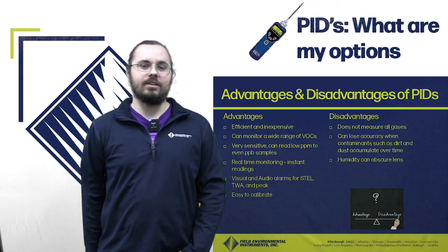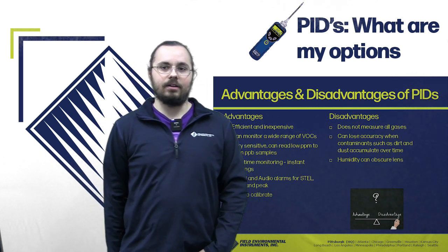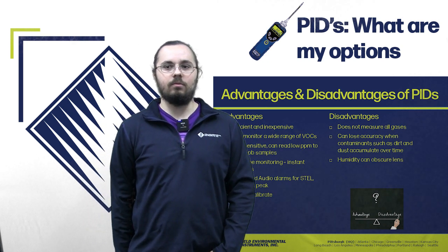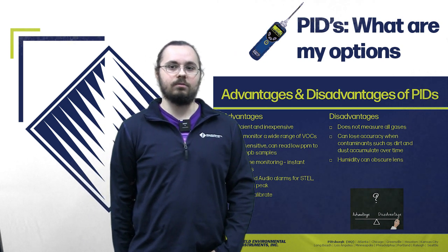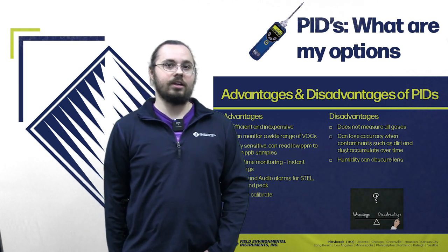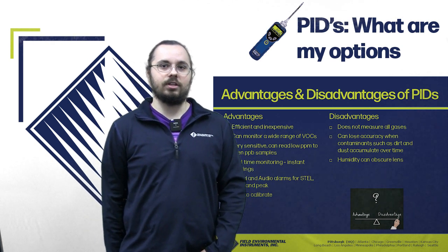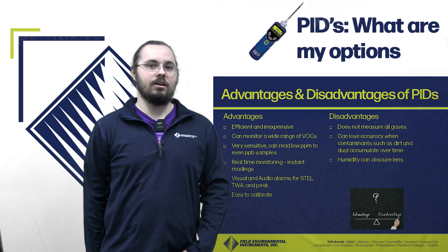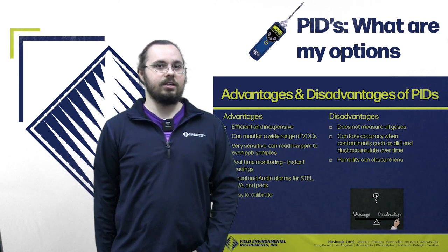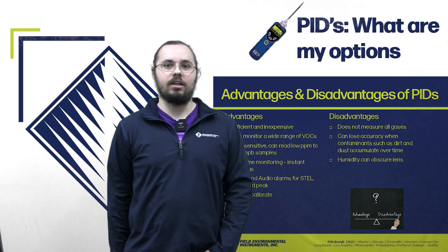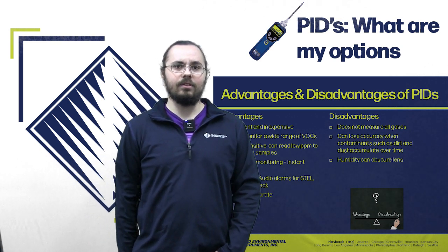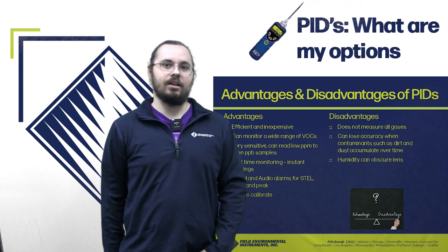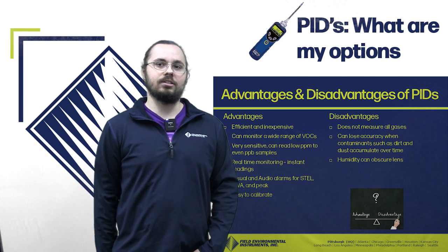Biggest advantage to these is that they're efficient and inexpensive. They can monitor a wide range of VOCs and are very sensitive, monitoring from low ppm to even ppb samples. They give you real-time monitoring, giving you instantaneous results on the screen as you go. They also include visual and audio alarms for STL, short-term exposure limit, TWA, time-weighted average, and peak limits. Last thing is that they're easy to calibrate. Most of them are only calibrated with a single gas and can be used in a wide range of applications.